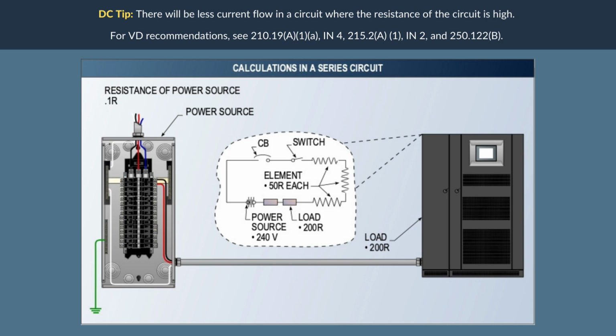For example, with a voltage drop of 34.275 volts across each 50 ohm load, what is the voltage drop across the 200 ohm load? In step 1, finding voltage drop, Vd, equals 0.6855 amps, multiplied by 200 ohms, which equals 137.1 volts. Therefore, the voltage drop across the 200 ohm load is 137.1 volts.